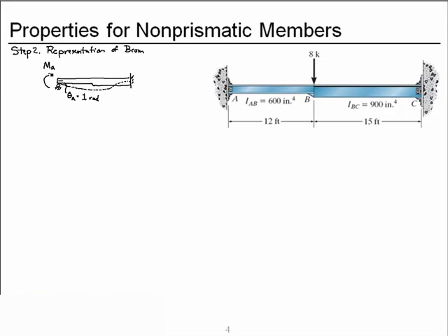So when I apply moment, we'll call it M_A, to this structure with the different moments of inertia partway through, we draw our elastic curve, our deflected shape. We're looking for the moment required to give us exactly 1 radian of rotation or slope at that end. And I'll point out this is a negative rotation, so let's call this -1 radians.